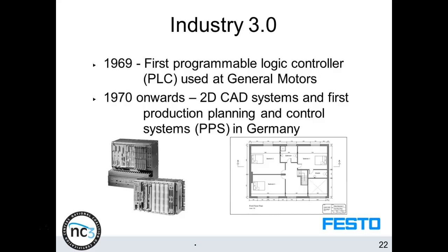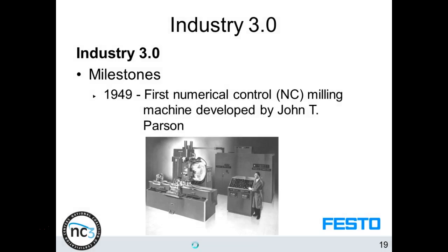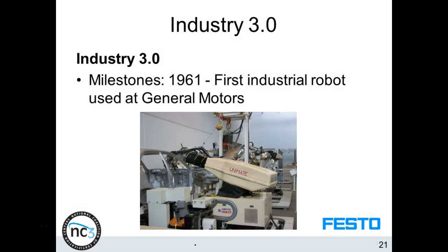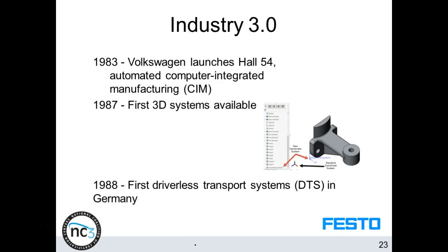Programmable control. So what these were were computers that were adapted to run machines. They weren't designed to run machines. They were adapted to run machines. Okay. A programmable controller is an industry-grade computer that's designed to run machines. So they're very rugged, right? You still have to take care of them. You can't play softball with them. But they're very rugged, and they're designed to run machines. And they program in a language that most electricians understand. We call it ladder logic. So PLCs, that's the main way we program them, even though we do have several ways.